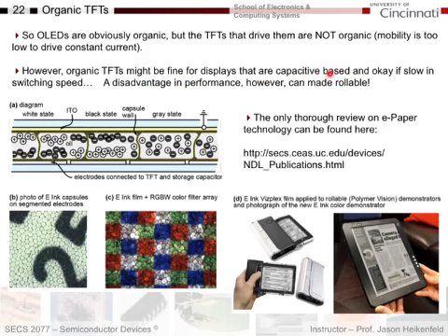And so one example of how you make a rollable display is e-ink, which basically has a charged ink where if I put, for example, a positive voltage here and a negative voltage here, that attracts the negatively charged black pigment particles in a fluid to the top and the white ones to the back, so that area of the pixel will look black. I could do the opposite, put negative here, positive here. That will reverse the positions of the particles.